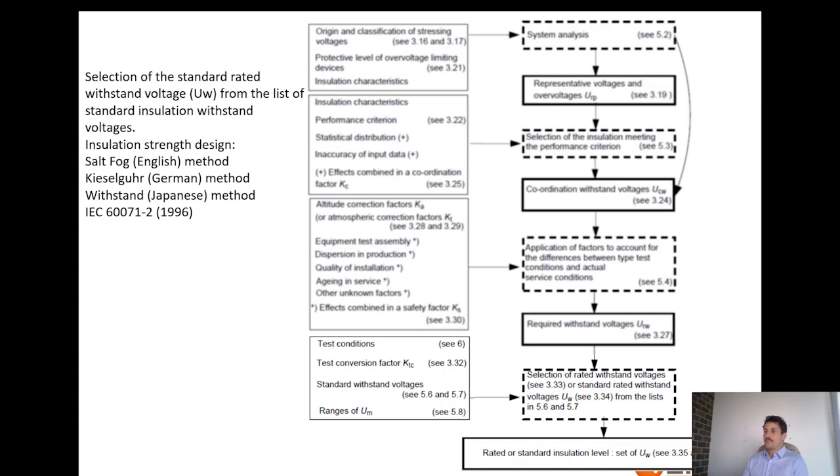And the last step, when you are at the step above, you have all these coefficients, you will get a value of voltage, max voltage for each equipment. And so then it's basically going through the list of BSL and BIL, according to switching or lightning, and select the equipment you want, basically. So the direct BSL just above what you've selected, the voltage you have.